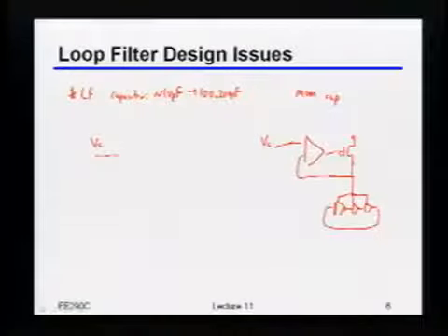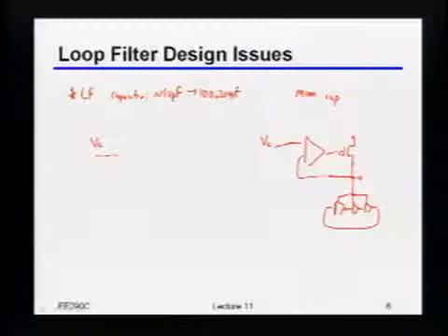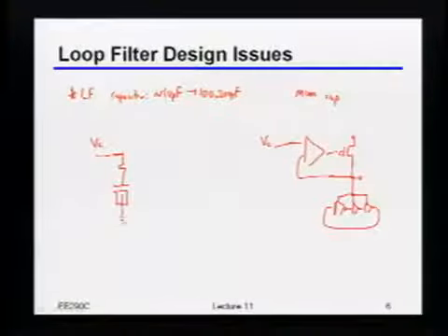Well, now I know that this control voltage here is going to have to be at some reasonably positive point, because otherwise my ring oscillator is going ridiculously slow, right? So that means I can guarantee there should be some reasonable bias, which means I can probably get away with putting a MOS cap there. Okay? So just as an example, you might build that as something like this.